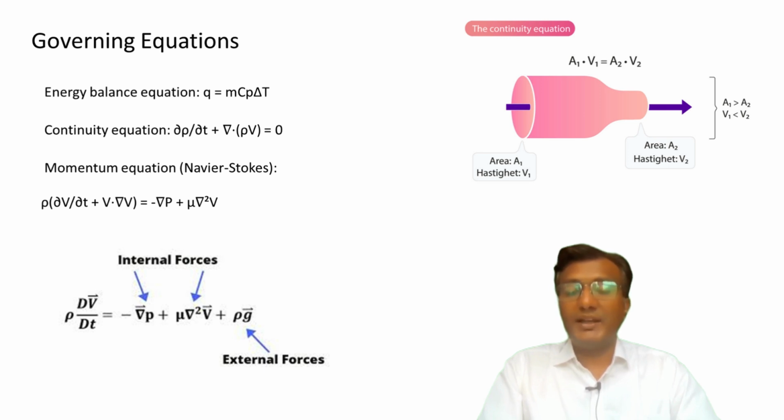The Reynolds number, as we know, determines the flow type, whether it is laminar or turbulent, which is based on the fluid's velocity, density, viscosity, and the length scale. When there is a turbulent flow, it is going to enhance the heat transfer due to the increased rate of mixing. The Prandtl number, as we all know, is a ratio of momentum diffusivity to thermal diffusivity, which also reflects how momentum and heat are spread in the fluid.